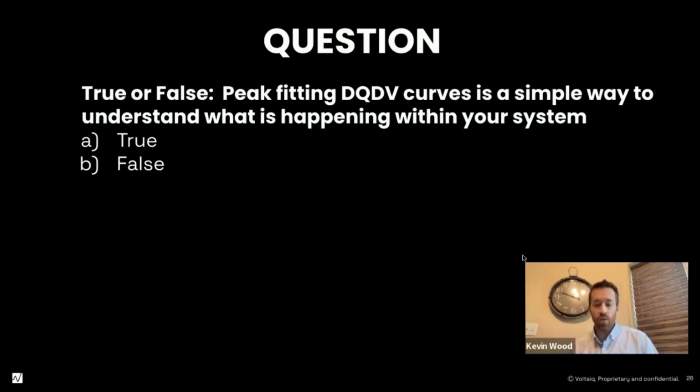There's also a lot of work out there on using DVDT, specifically within rest steps, to also help identify lithium plating as well. So that may be something that you would be interested in taking a look at.